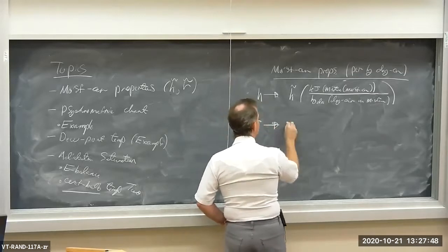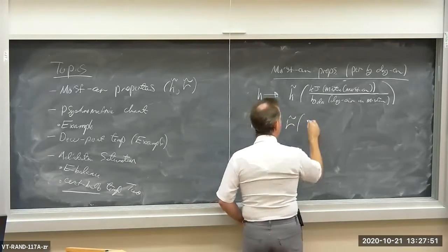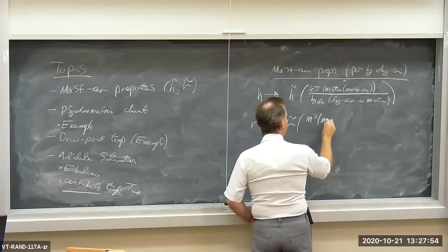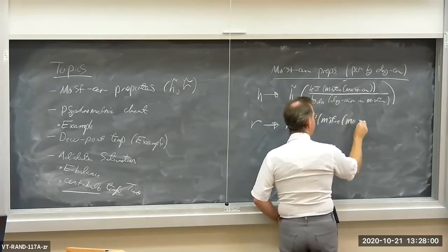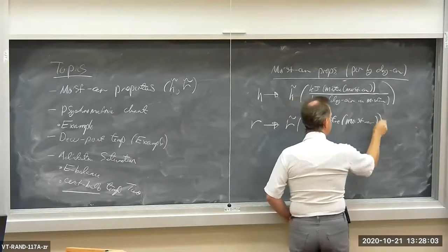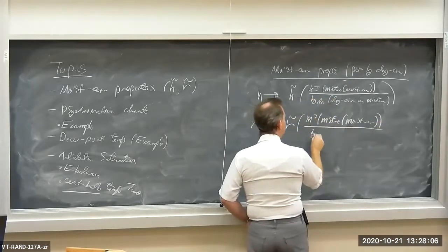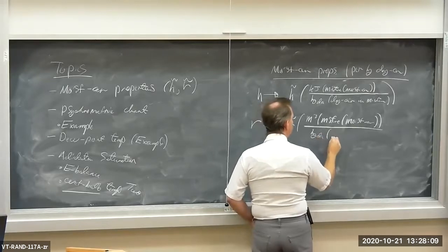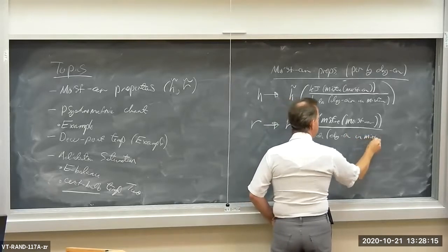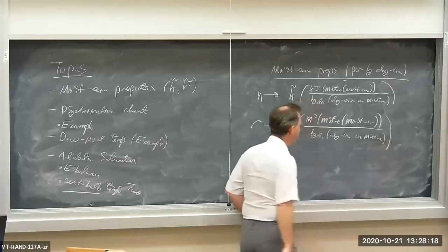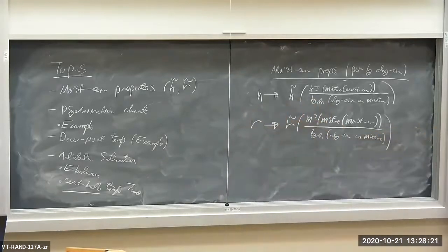So specific volume becomes specific volume tilde, and that becomes cubic meters of mixture, and what I mean by that is moist air, divided by the kilograms of dry air in mixture. Okay, so when you see these tilde quantities, think in the denominator per kilogram of dry air. Okay, so that's how we're going to be evaluating properties for most of these problems in the future.